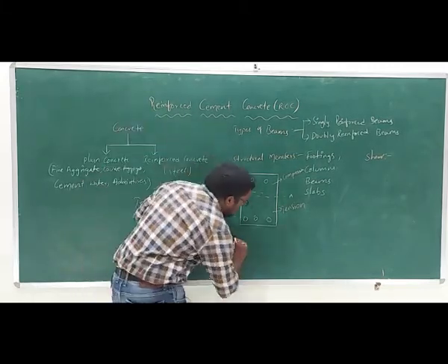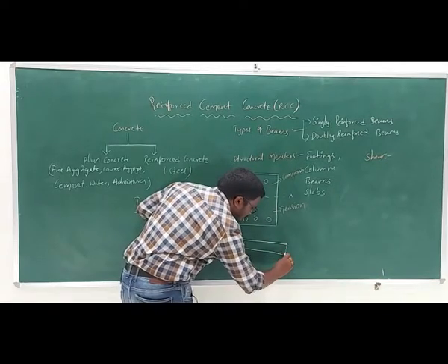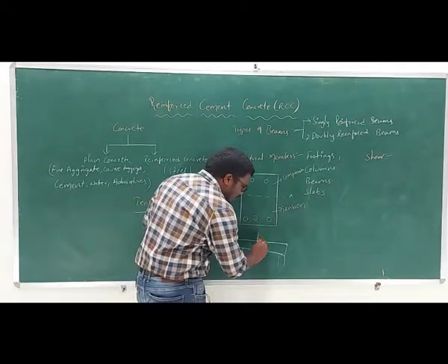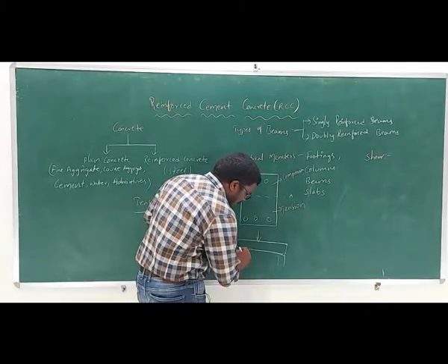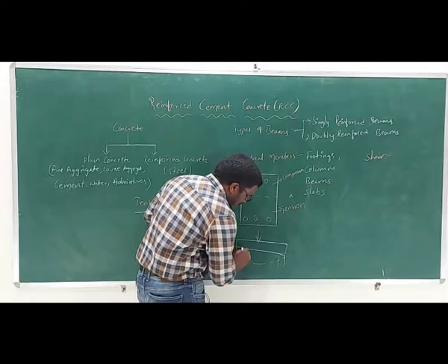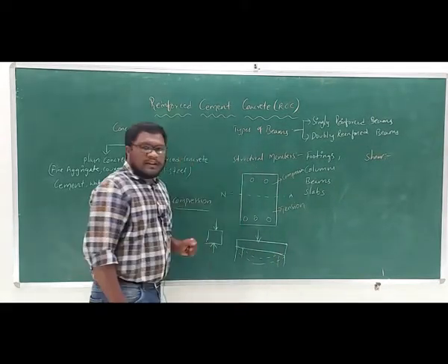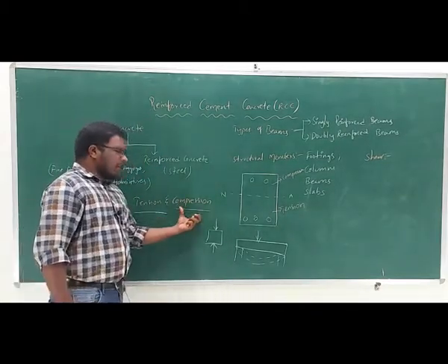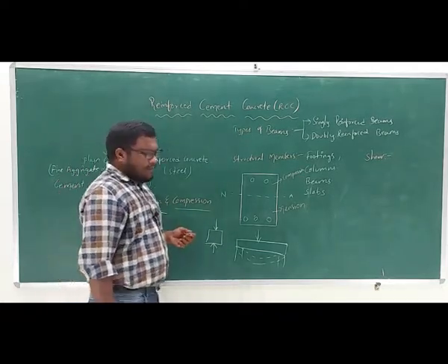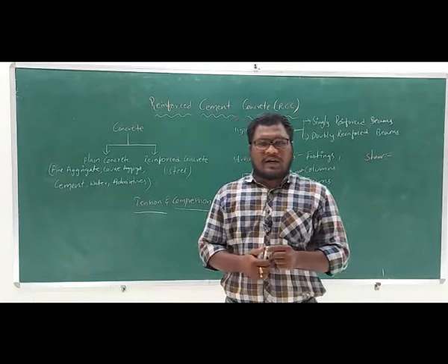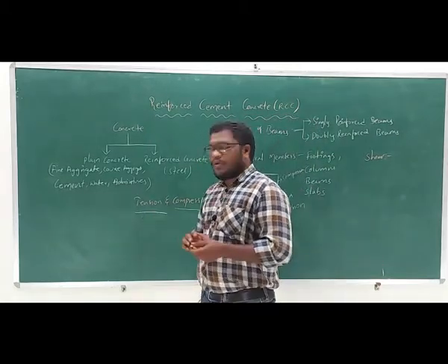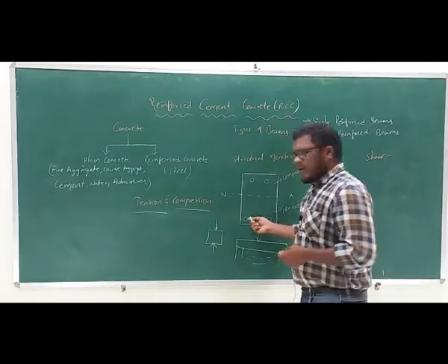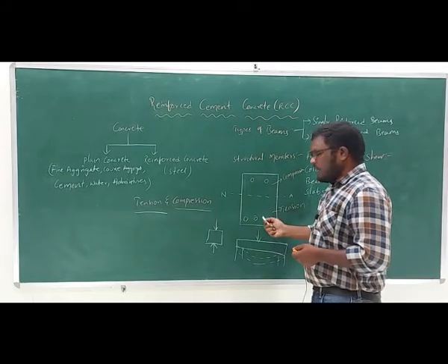But when you go for a beam, here the supports are there. Now due to the action of load on the beam, what happens? Deflection occurs like this, and there might be chances of failure. So we can say that concrete is good in compression and weak in tension. To make the concrete withstand tension loads, we are going to provide the reinforcement in the tension member.